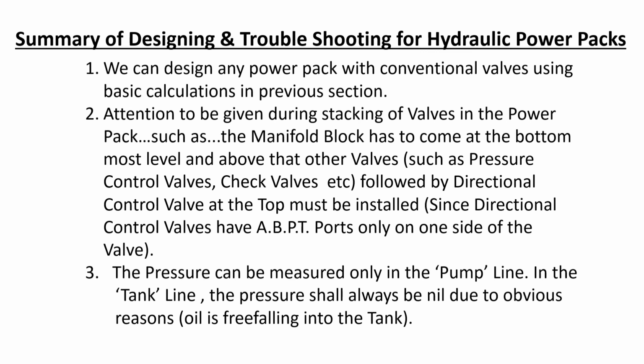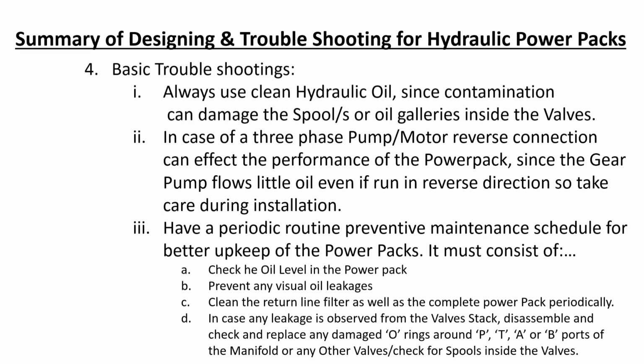At the topmost must be installed, since direction control valves commonly have ABPT ports only on one side of the valve, and then pressure can be measured in the pump line. In the tank line the pressure shall always be nil, for the obvious reason that oil is free falling into the tank.